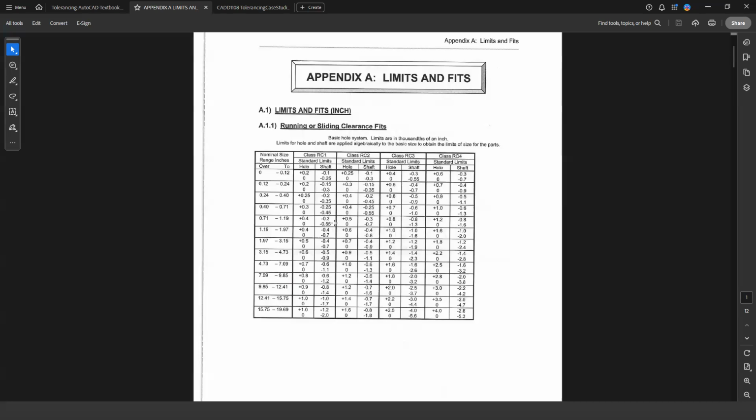And what we need to be able to understand is whether there is a reference sheet somewhere that can help me remember. You're never going to memorize any of this, right? It's just that if I ever see this in the industry, or if I'm using a program like Inventor and I see that I could apply this weird coded-looking class of fit, I would know, hey, that is a tolerance class of fit, because I can recognize the acronym, or what I call the hieroglyphics. I can say, oh, I remember that. That's tolerance-specific dimensioning. And you'll see this pop up in the program when you're poking through it in your life.